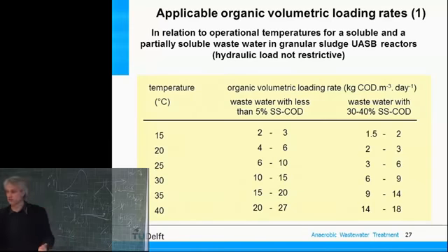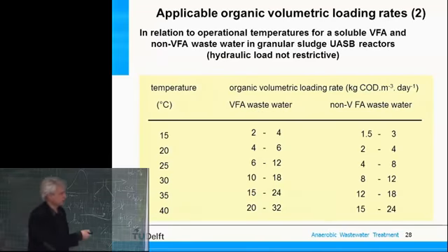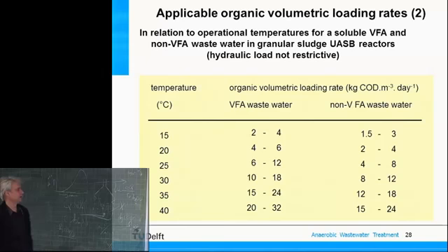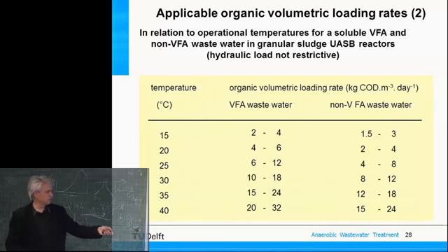I give you the example in Cuba of Finasse, very complex wastewater, with quite some suspended solids, and you cannot have the same residence time or applicable loading rate in comparison to beer brewing wastewater. So temperature determines, and the complexity of the wastewater determines, what is the exact value of the applicable loading rate, this RV. Also with soluble wastewater, there's a difference in the type of compounds that determines the volume. Again, temperature is the determining parameter, but also whether we have a VFA containing wastewater or non-VFA containing wastewater. VFA means volatile fatty acids.